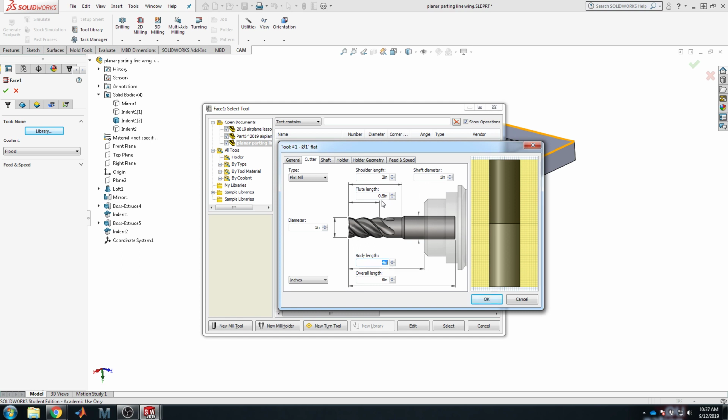We're just going to be flattening off the top, so really it's this wide bottom face that's going to do most of the cutting, maybe a 1/16 of an inch of depth. We're not going deep with this tool, we're just flattening the top surface. So we'll say, okay, 1 inch shaft diameter, actually I think it's 0.5 technically, so the tool looks more like that. These are approximate. What you would really be doing at this stage is hopefully having the tool you're going to cut with in your hand with a set of calipers, measuring diameter, or taking measurements on the tools. If you're holding any of these tools ever, keep in mind those edges, by definition, are extremely sharp.